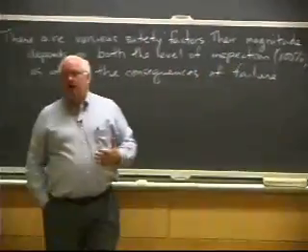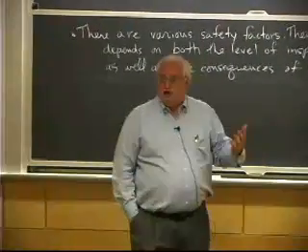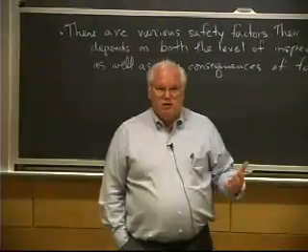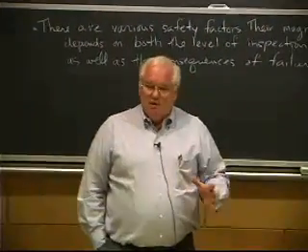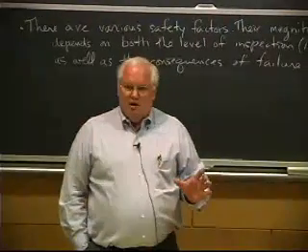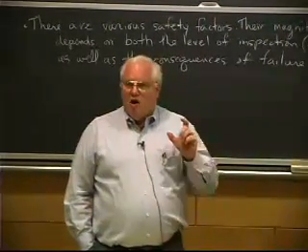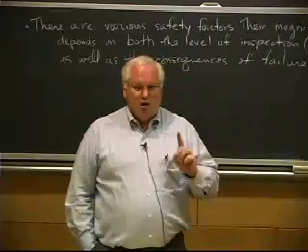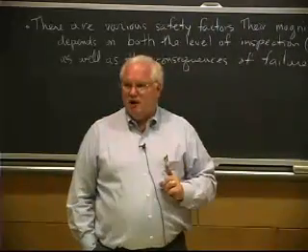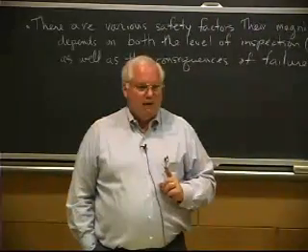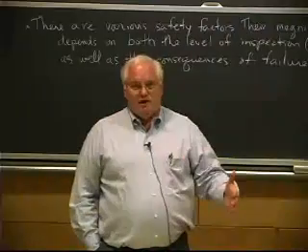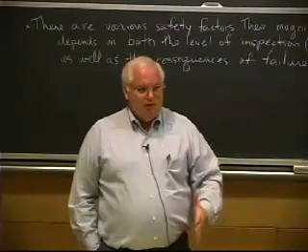If I take a ladder, which is another structural element, or scaffolding, typically there's no redundancy there, and OSHA actually requires a 400% safety factor, not on the design, but on a proof load type of test, okay? Actually, it is on the design, but then they have to do a design verification test.